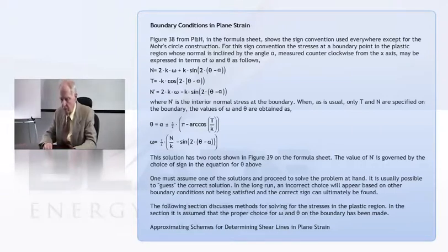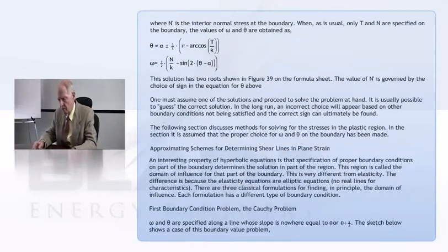Now, there are several schemes that are used to form the kind of solutions that we're going to get. And these come under the general category of slip line theory. And that makes a little bit of sense, because if you recall, on these first and second shear lines, those were lines on which the shear stress was equal to K. And so your stress strain curve will say that you're going to have shear on those lines.